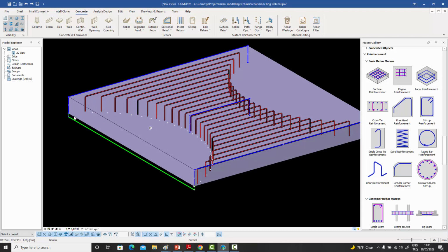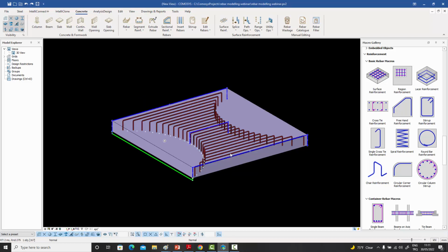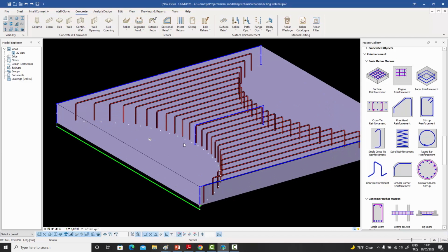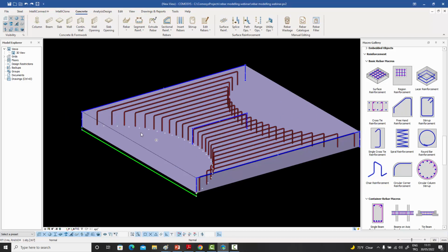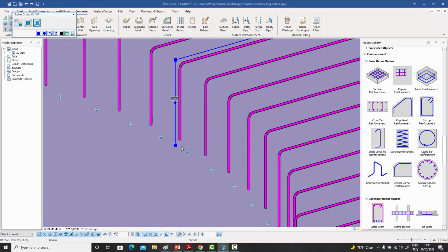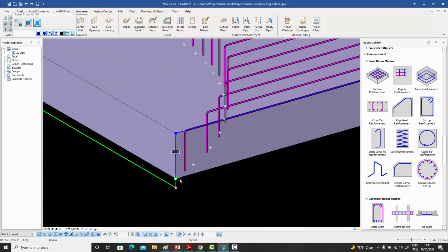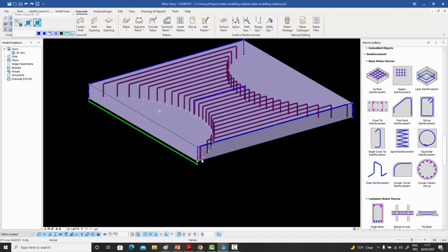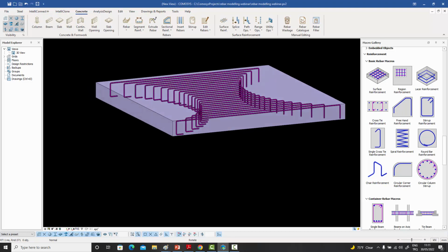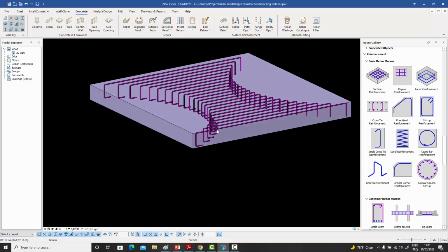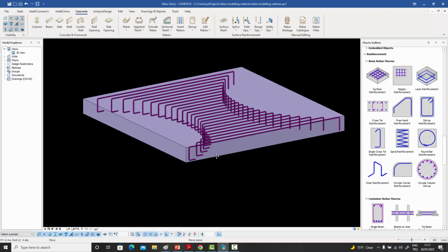Let's select the rebars. And let's say you had forgotten a point in the original definition. If you remember, I had defined the bar like that. But what if you had forgotten a point right in the beginning? Well, what you can do is you can select this endpoint. You can zoom in and select this one as well with pressing Control, and you can zoom in and press this one as well. And after having selected all three, if you could just say add point, then a vertex is added at the beginning, at the start point, and now you have an additional definition point in your path.